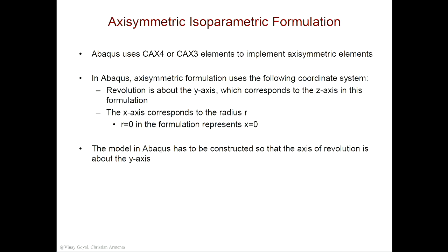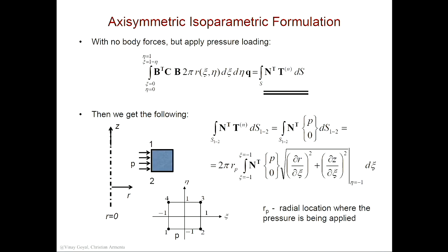I do want to cover, I explained it here in words, but I think visually was better. One point I want to make is how to handle the tractions. That can be a little bit tricky here. So these tractions need to be considered carefully. You can see here the traction in this case, if I'm applying pressure to a single element. Don't you agree that this pressure is going to cause a hoop stress? Yeah, because if you revolve this ring, I'm applying pressure to that ring on the inside, it wants to expand that ring, right? But the ring has stiffness, so it's going to resist that. And so it's going to produce a stress, which is PR over T. And hopefully, if I were to do this in Abaqus, it should be P times R, mean radius, divided by thickness. It should come up about the same, okay, if I ran this in Abaqus.